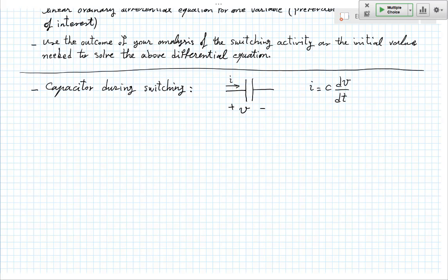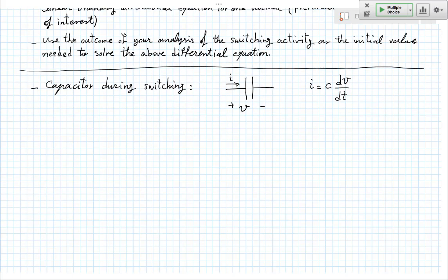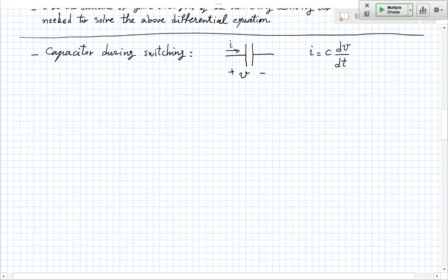What's the flow of water that I should put in? A lot, meaning infinity, if I want it to happen in no time at all, right? If you want to fill up your bottle in no time, you need an infinite flow of water. So same thing here. For that reason, a capacitor will obviously prevent or resist an abrupt change in voltage, unless you somehow force it, which, as we've seen in examples in the past, you should not do in real life, right?